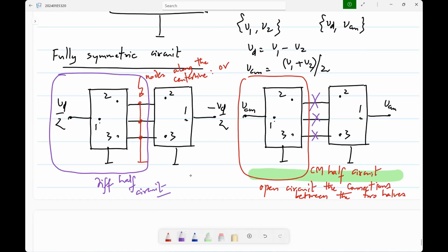Because one side was going through the parasitic pole, one half of the current, the other one was not. Such things will not be here because it will be fully symmetric. You don't have that extra pole zero in the fully differential op-amp. So overall, the fully differential stuff will be better. And of course, it's very commonly used in analog IC design. So that's something that you have to learn. But whatever you know about single-ended feedback loops will be helpful, because if you look at just the half circuit of the fully differential circuit, you will get single-ended circuits.